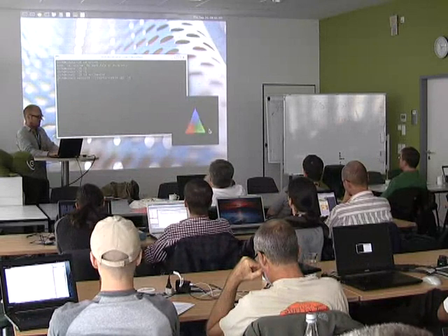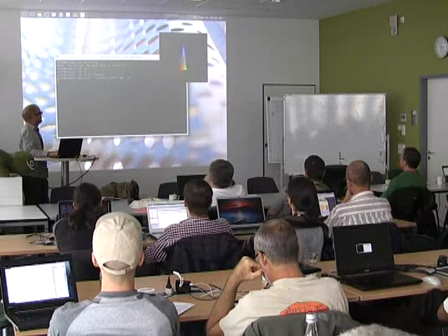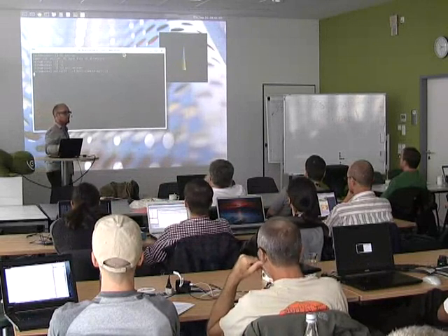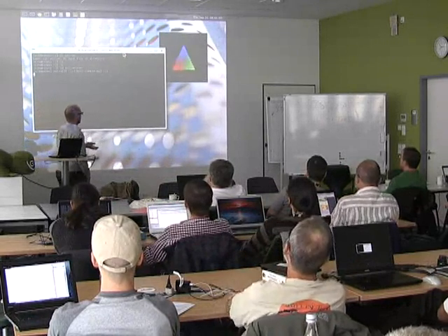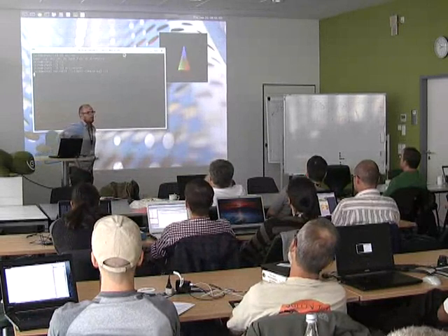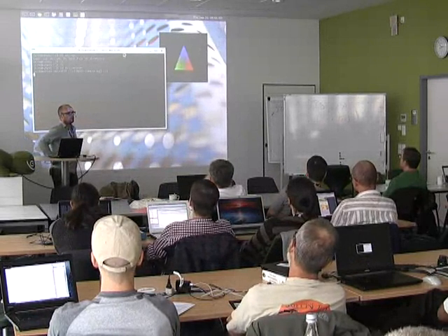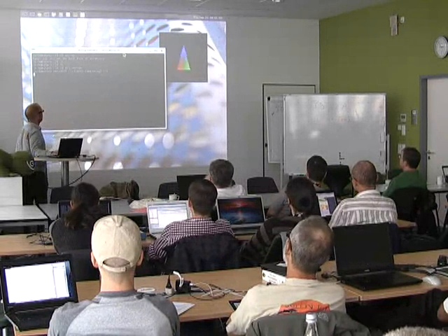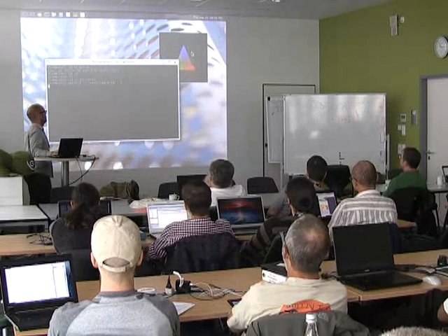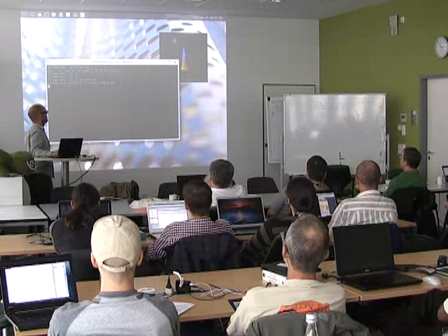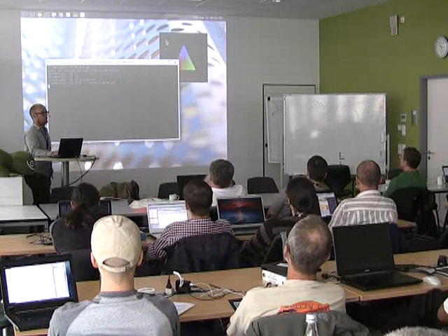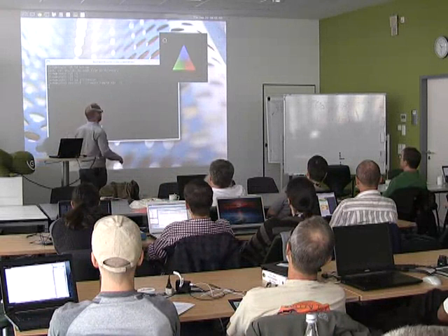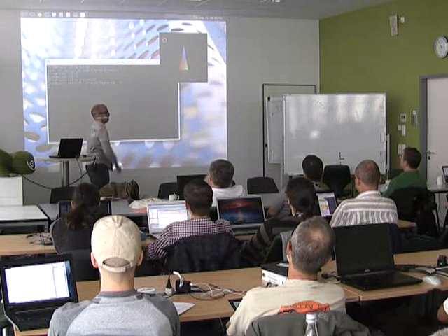So here's a spinning triangle, and this surface is an opaque RGB surface. And on this Intel hardware, we actually have overlays that can take either YUV surfaces or RGB surfaces. So in this case, when my terminal is on top of the other surface here, well, there's nothing we can do because we can't use a hardware overlay. But when I pop this one on top, we flip that surface to use a hardware overlay.